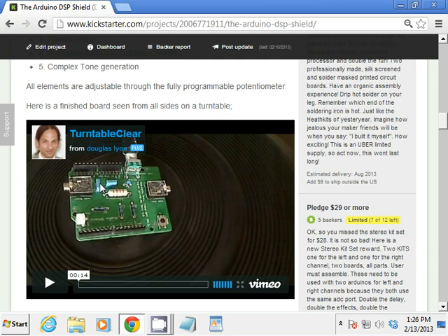I didn't think people would buy this. This is 10 bits in, and I'm using the most rudimentary of output. People seem to be okay with it. But I have a feeling that if you had a high precision A to D converter and a high precision D to A converter on a shield, people would want it. We already know something about buses, SPI, I2C. We know Arduino buses support these things, and there are libraries for it. Very good to have software.